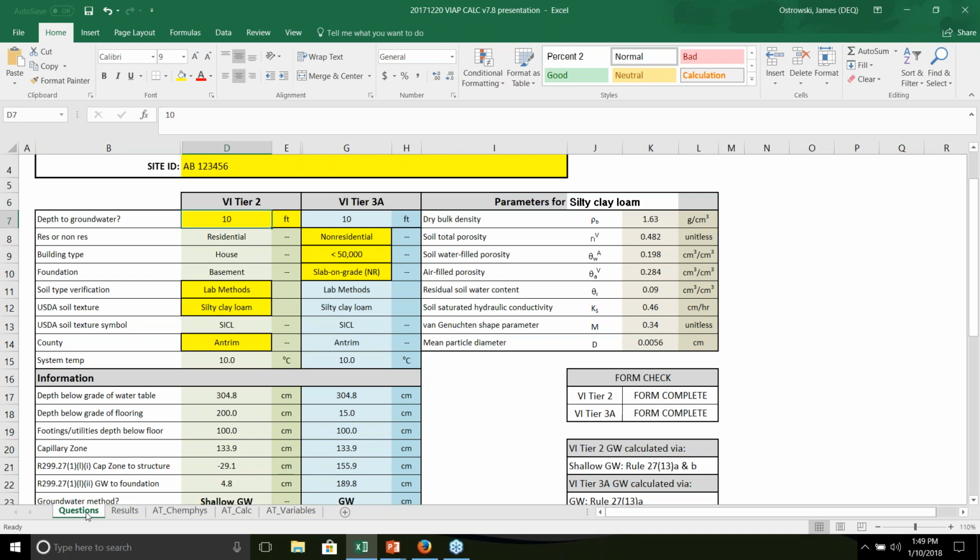I think it's important to understand, though, that the historical data will be able to help guide us in what the soil type is. There are other tools out there that will also help in that guidance, such as the USDA Soil Classification Survey page, which identifies across the state, on a very wide range, what you can expect the range of soil types to be on your site. Those will help guide us: if we can identify what the soil type on our site is, we'd be able to do the sensitivity analysis to see how much, if any, change that would mean for us.